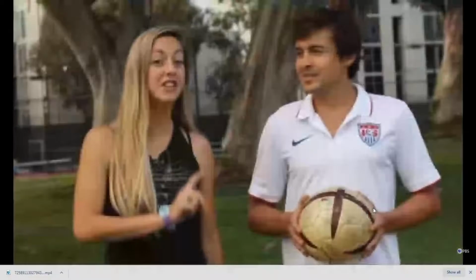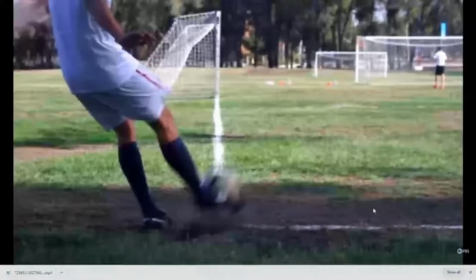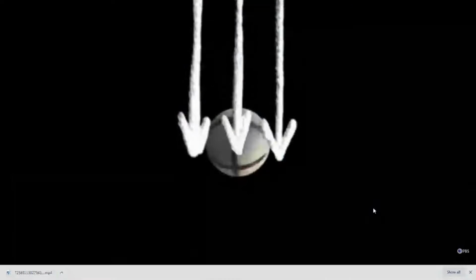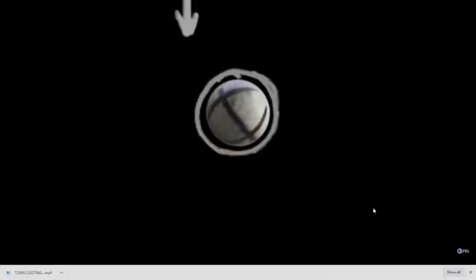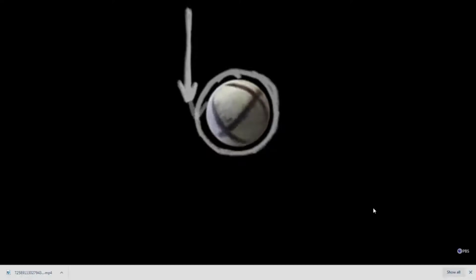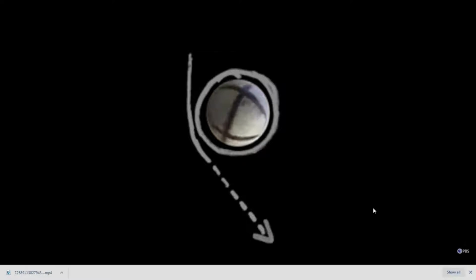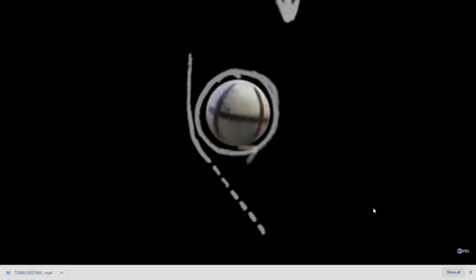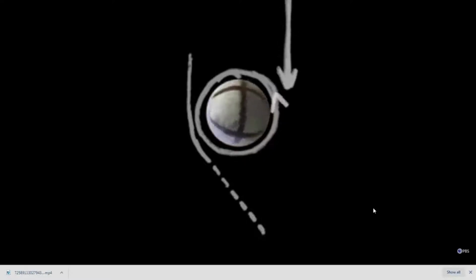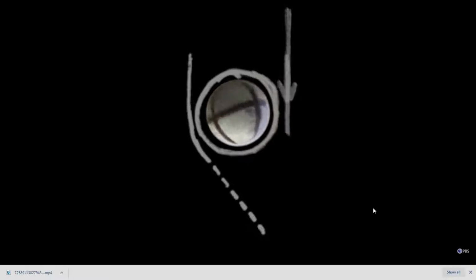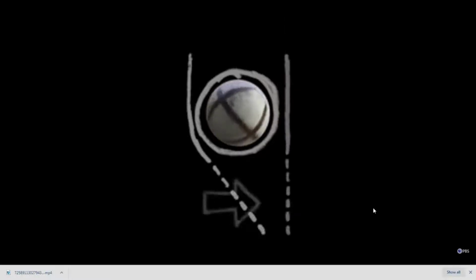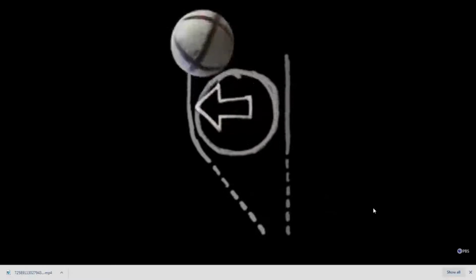As Kyle kicks the ball with his right foot on the right side, he imparts a spin on the ball. The ball traveling in this direction means air is flowing across it in the opposite direction. But right near the ball, there is a thin layer of air dragged around. As oncoming streams of air pass the ball, the side moving in the same direction as the spinning ball is accelerated, follows the curve of the ball, and is deflected off to the right. The side that is moving against the spinning ball meets opposing air and can't continue around the ball. It slows down and goes straight. We end up getting a net flow of air to the right, and the ball must move left.